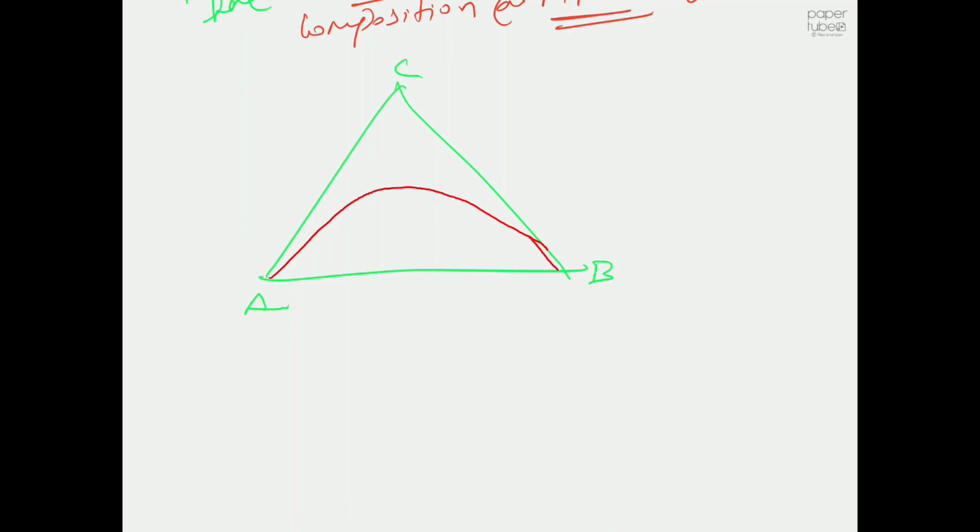So if you have a good liquid equilibrium curve, and if I have tie lines like this, if you don't remember what a tie line is, you have to watch my previous lecture for sure. So this is tie line 1, this is tie line 2. If I ask you to draw a tie line that cuts through this point, you cannot just use a scale and draw like that. Yeah, this is wrong.